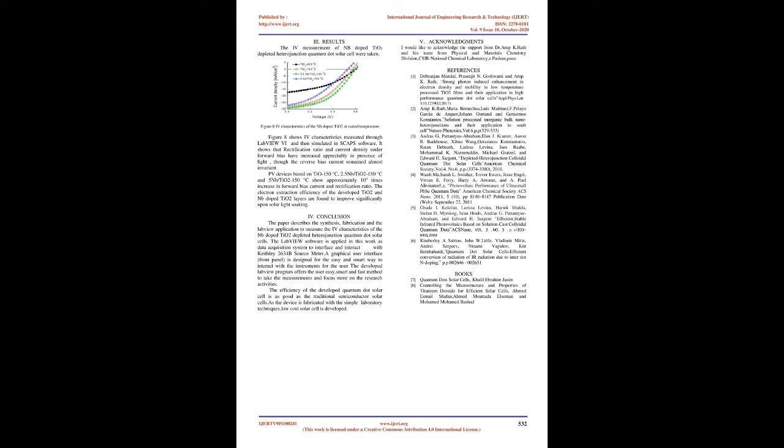The VI starts with the opening of the VISA session for the Keithley 2634B instrument. VISA is the Virtual Instrument Software Architecture API. NI-VISA is an API that provides a programming interface to control GPIB and other instruments in NI application development environments like LabVIEW. The API is installed through the NI-VISA driver. VISA Configure Serial Port VI initializes the serial port specified by the VISA resource name to the specified settings for the Keithley 2634B precision source meter.